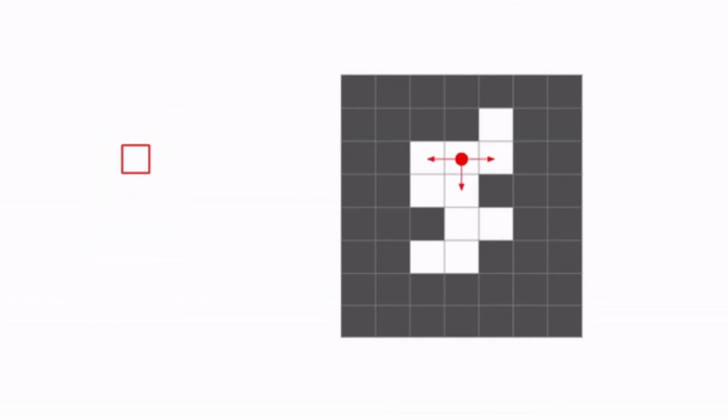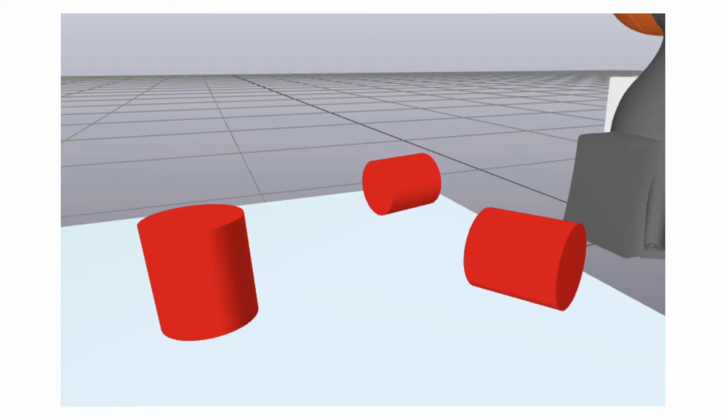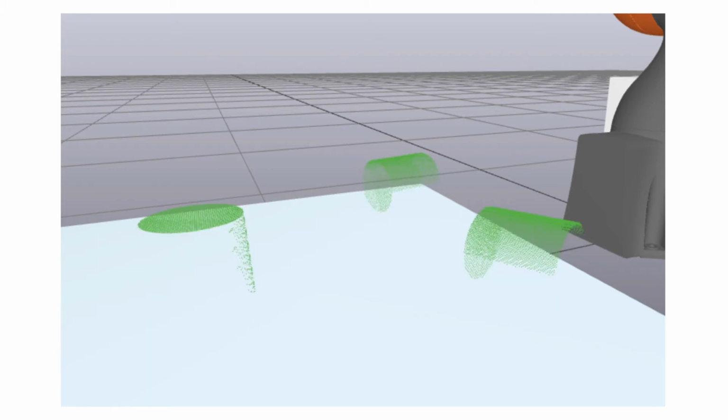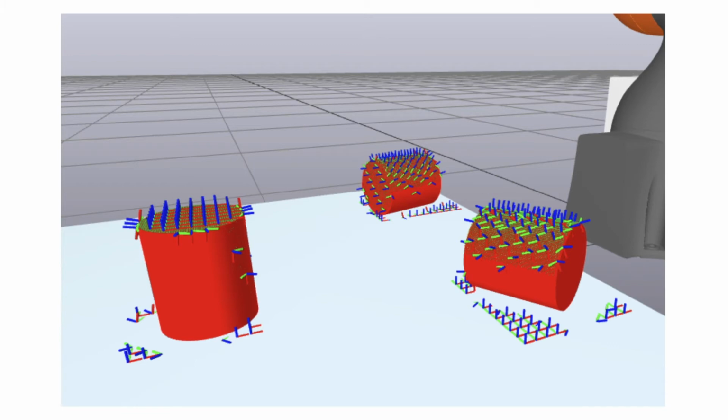And now that we can distinguish the objects in the scene, we can just use what we learned in lecture on each object to produce a point cloud and estimate surface normals. And then this is where we deviate from class again. We had a piece on antipodal normals as a heuristic for generating grasp candidates, but since in our project we were only using a camera from above, you can see in the vertical can case on the left, there likely isn't an antipodal pair of normals.